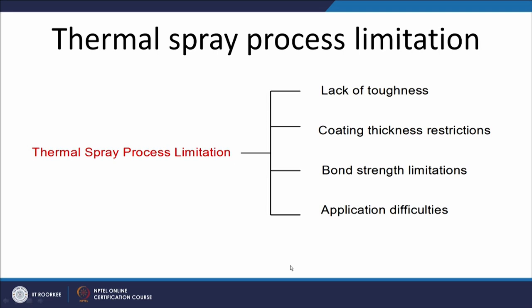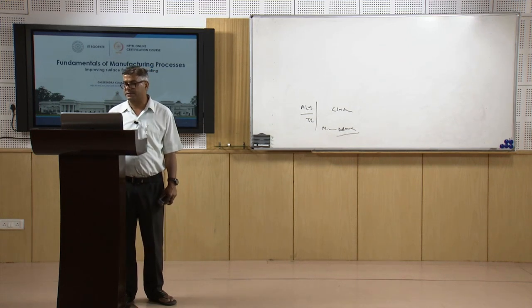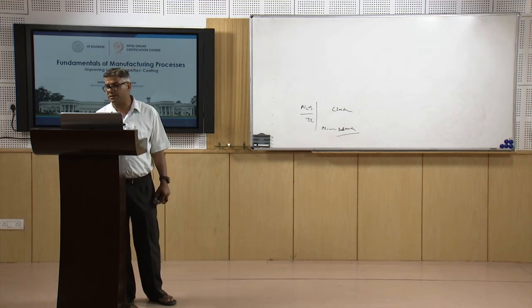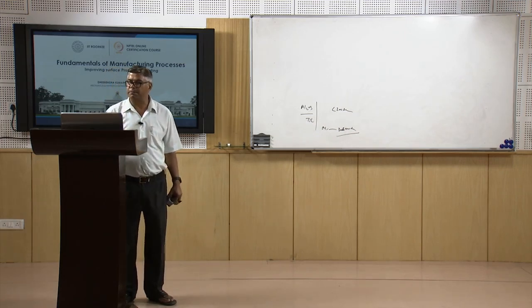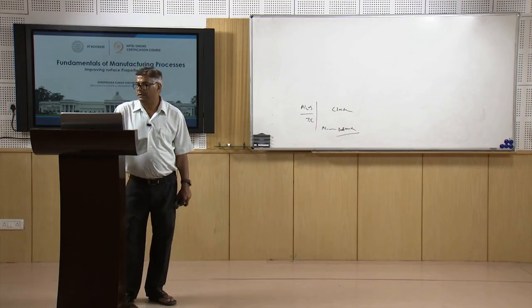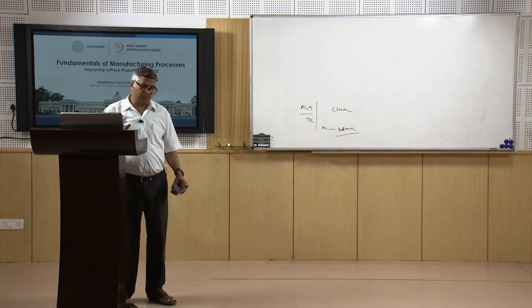And application difficulties are that it cannot be applied in all kinds of situations. It works in the factory environment, and since the velocities are too high with the high velocity processes like HVOF and detonation gun process, very rigid systems are needed for spraying, so it cannot be applied in all situations.